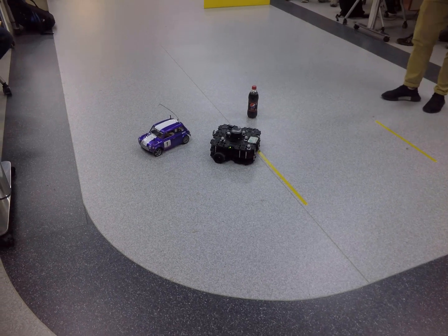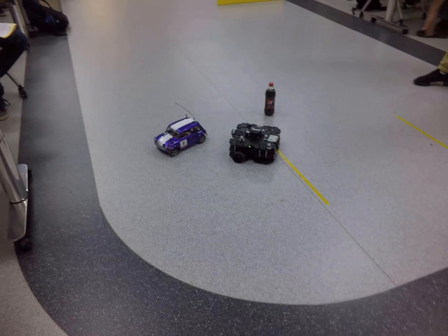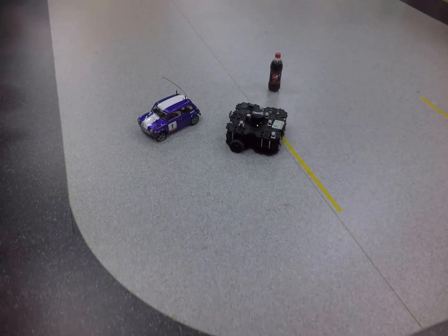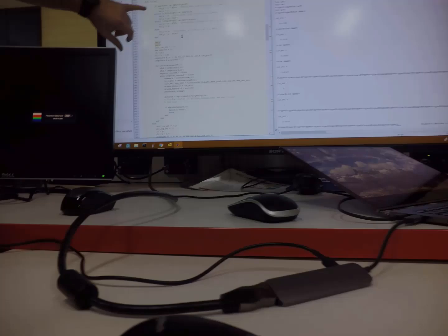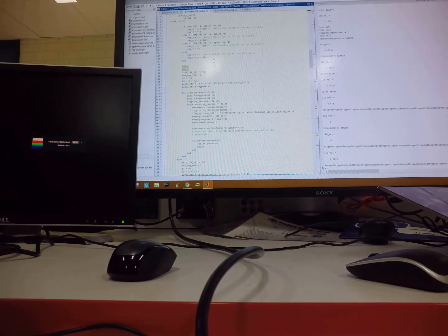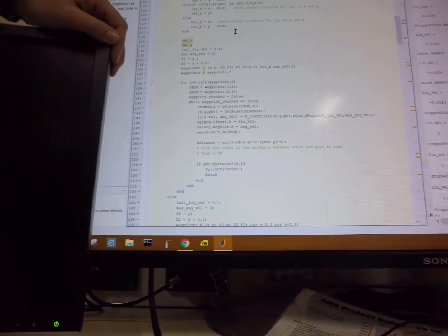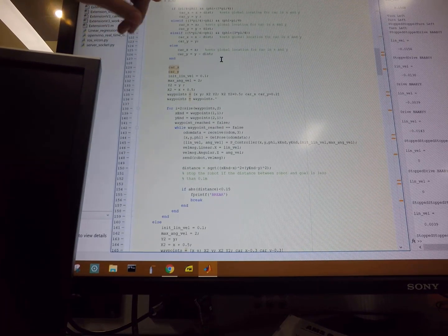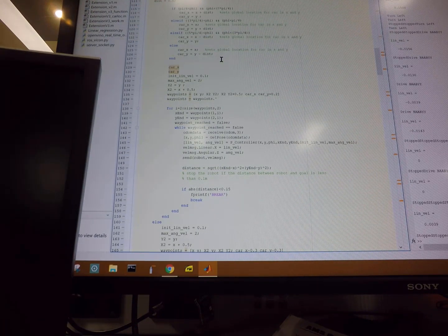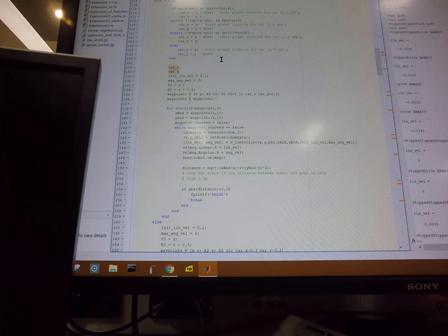So the idea is, if I had a bit more time, I would obviously refine my waypoints a little bit, and if the car was still driving, it would pick up the car again and continue on the car. The car's location is with reference to the X and Y coordinates of the robot's location using the Vicon. At the moment, we've just got half a meter added on, just so roughly the bot and car will always be half a meter apart-ish. And then I've split it up into the 4 quadrants, so it should be pretty repeatable in any angle.